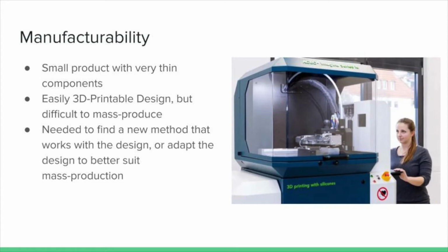The original design was found to be difficult to manufacture using traditional mass production methods. Prototypes were easily 3D printed, but the thin components of the material made it difficult to manufacture using other methods, particularly injection molding. Our challenge was to find a new method that would better suit the current design or adjust the design to better fit the injection molding option.